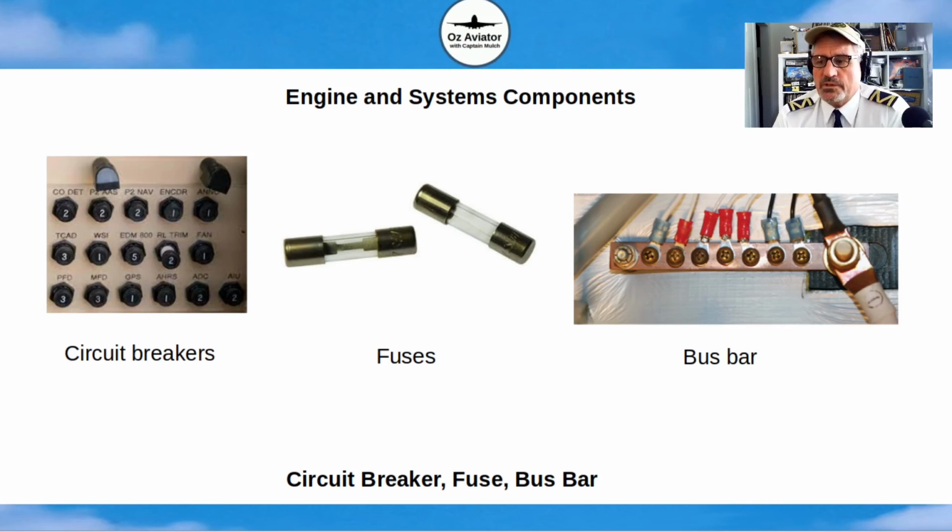So there's a switch that is off for the avionics bus, the avionics master switch. Once the engine's started and the aircraft's up and running, you then flick the avionics master switch on, and that provides power to the avionics bus, which then enables you to turn on your radios, transponder, etc.